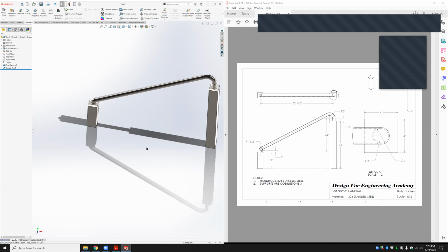So when you look at the path, a good assumption to make is that what you're trying to draw is the center line, right? The path. Yeah. So a good assumption to make is that it's a smooth path. And mathematically, that would mean that you have an arc or part of a circle right there, right? So when you have the straight line, you're going from a curved line to a straight line. If you want that to be smooth in math, that'd be called tangent, right? The straight segment is tangent to the arc or the circle. So you can make a relationship between the linear line and both your circles to make a tangent.